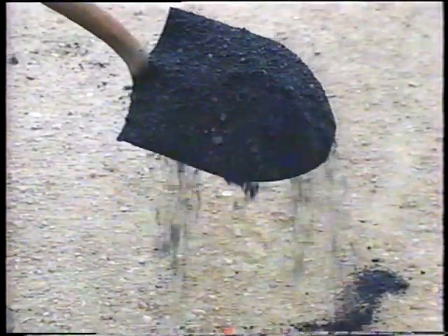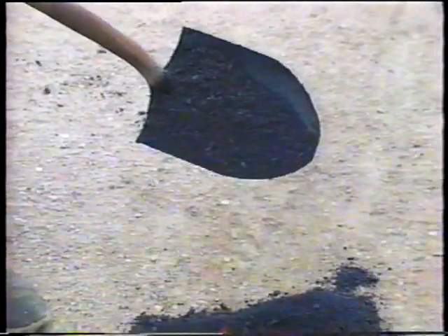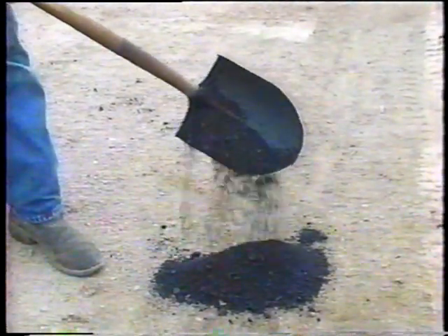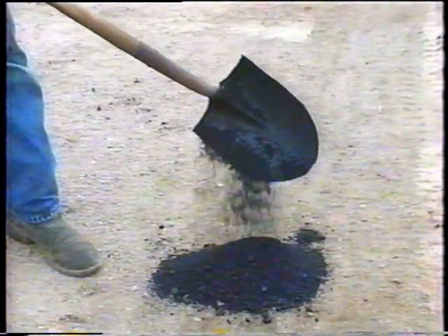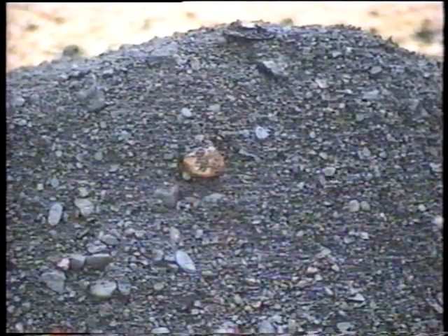Another clue that the mix might be too cold is a stiff appearance. This can also be evidence, though, that there's not enough asphalt in the mix, especially if the mix looks dull. No, I don't mean boring, I mean lacking the normal shininess of fresh mix. A stiff, dull mix is a sure bet you'll have binding and compaction problems.